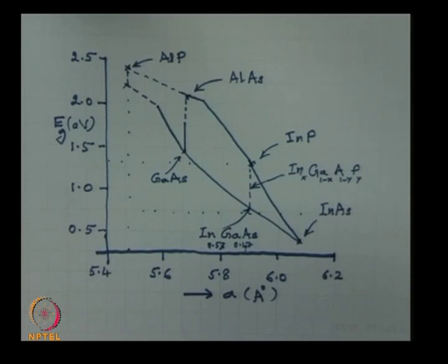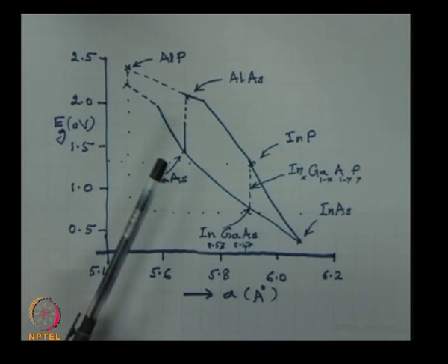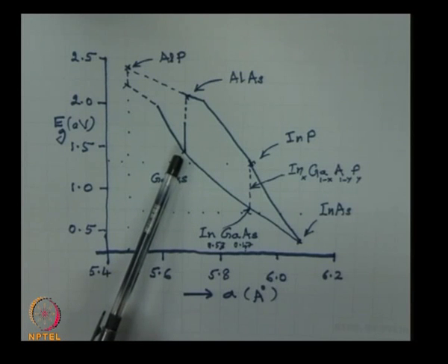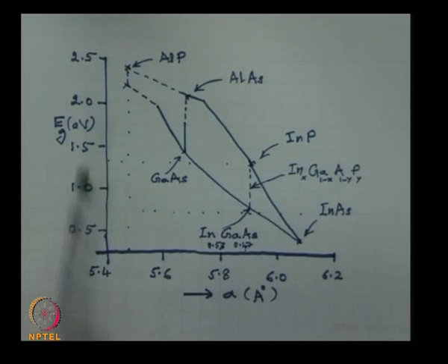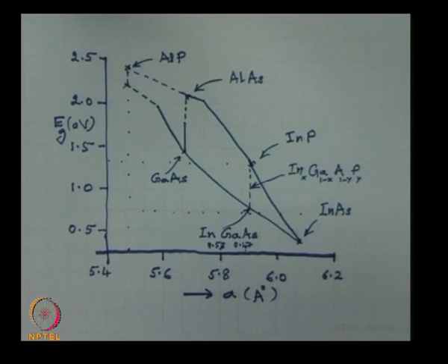So, see the plot, gallium arsenide is here. Gallium arsenide band gap energy is 1.42 eV, you can see here 1.42, and lattice constant is 5.65. If you go down here, you can see it is 5.65. So, the plot is simply you have pairs of x and y, you simply plot the points first. And then it is linked, gallium arsenide from here is linked to indium arsenide. This is not a theoretical plot, these are experimental plots.